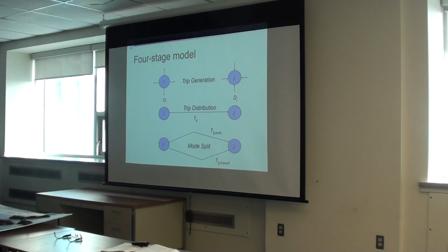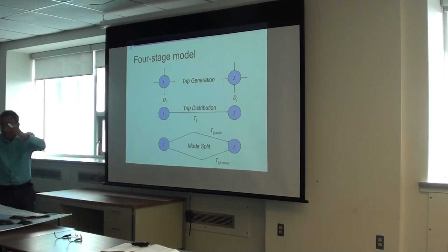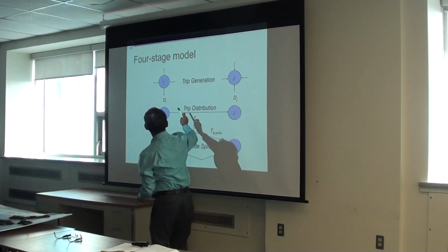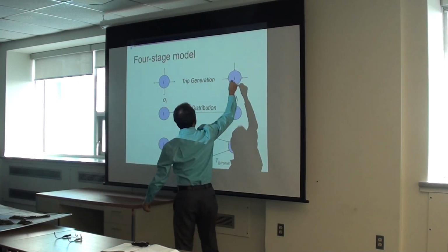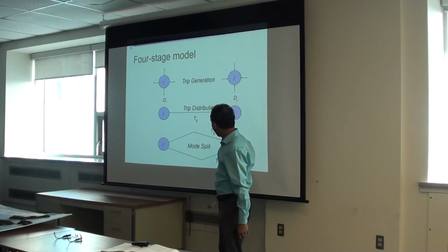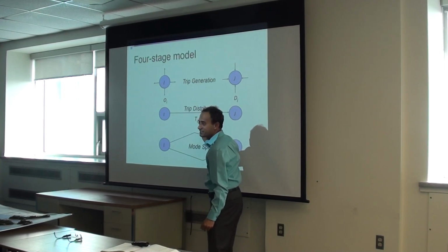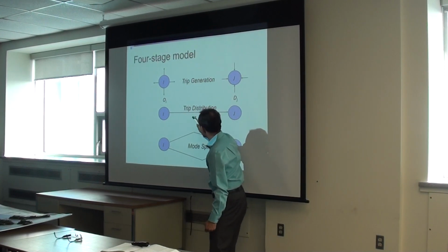So we know that. Now in the second stage, we don't know the trips yet, we just know the generation of it, right? In the second stage, we see, if there are 50 trips generated here, how many of them are going to Dartmouth, how many going to Halifax Peninsula? That's the distribution. So then we get the trip, both ends, right? In the initial stage, there's no end. So we know the flow, right? That's why you will see there is no connection here, only how many going out and how many coming in. And in the second, you can also look at the notation. So it becomes T, zone I to zone J. So we get the distribution of trips.